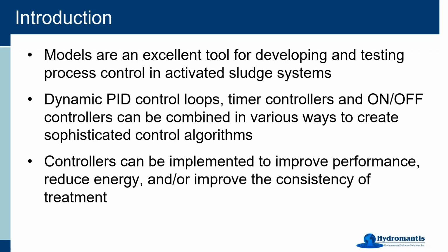So really those controllers, as I mentioned, depend on what you're trying to do. They can be implemented to improve plant performance, get to very low concentrations of effluent total nitrogen or total phosphorus, for example. Or maybe improving your performance is not necessarily getting as low as you can go, but maybe making your facility more robust. And maybe that's really where you need the controller. A big one, of course, that we see all the time with the clients that use GPSX is doing analysis where people are saying, how can I use control systems to reduce the amount of energy, particularly